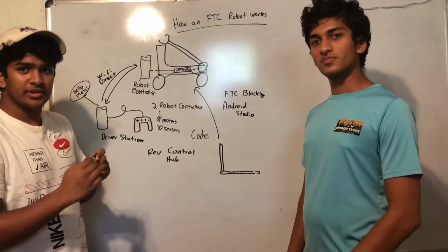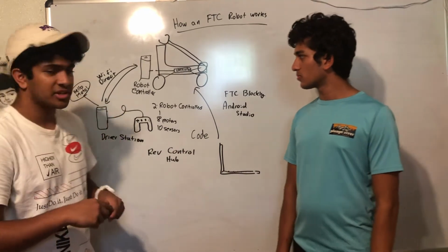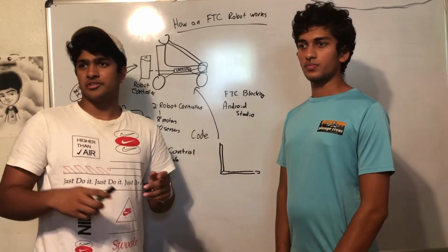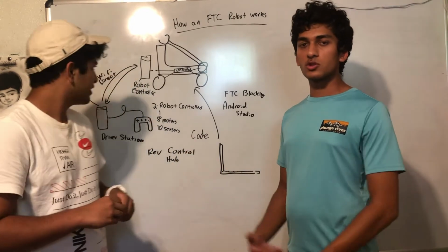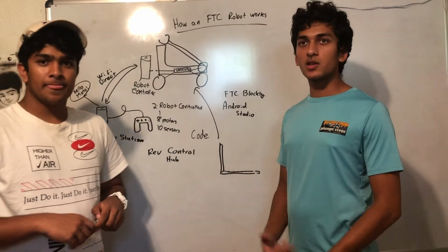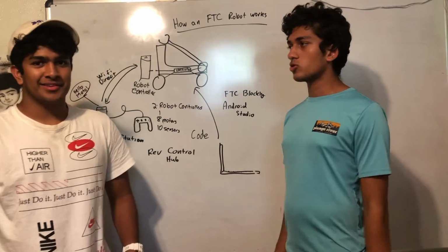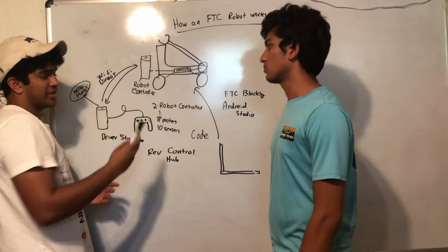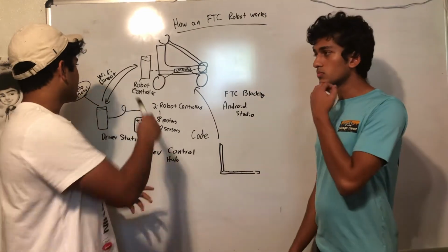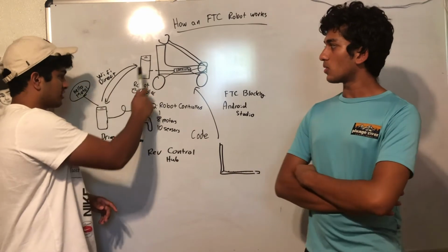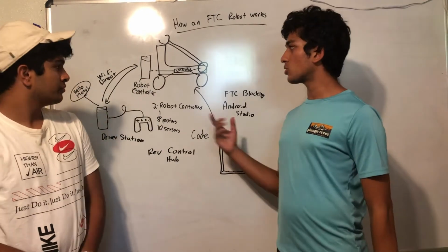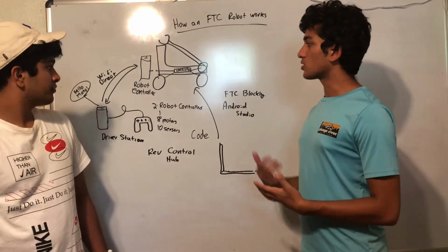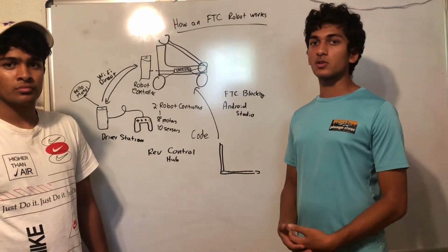Another thing you'll find is the field tech inspection person at the meets always checking for Wi-Fi signals. They'll tell you to turn off your Bluetooth signals and all that. Switches and stuff, Nintendo Switches, any peer-to-peer connections, because that can interfere with the Wi-Fi Direct signal. Big time. Think about all the robots at the meet that rely on this connection between the driver station and the robot controller. Try to be courteous to other teams. Turn off your Wi-Fi Direct if you're not in a match, because the more Wi-Fi signals in that building, the less likely teams are to connect well.